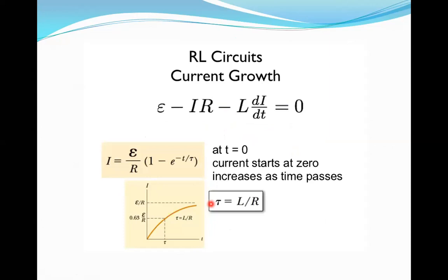After mathematical calculations and integrating, with the boundary condition that when time t is equal to 0 the current in the circuit is also 0, if you substitute, finally we get I is equal to E by R into 1 minus exponential of minus R by L into T, where we have taken tau as L by R. We will understand what this is.